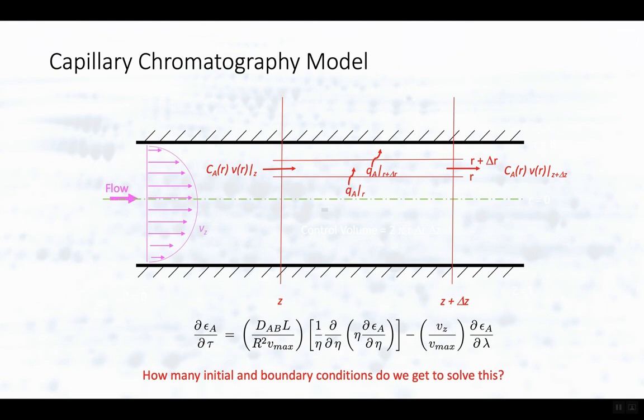All right, so let's continue with our capillary model, and let's get into the meat of what makes chromatography different from just flow through a pipe. And here we're going to do a material balance. This is how we got the model that we generated, was a shell balance. We look at a delta Z region of that pipe. We look at the flux going from the center point of the pipe out to the wall. Okay, that creates a shell that we're doing this balance equation around, and we write out our balance equation.